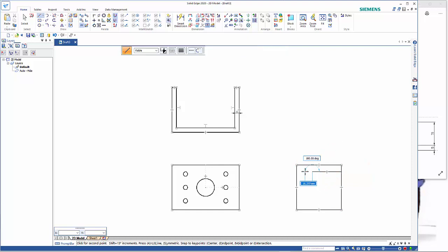If you come out to the left and hit the A key, that turns it into an arc. Then when I type in the arc radius, I can click to place that on the edge there. Likewise, I can do a fence selection on that if I hold the control key down to get rid of those extra bits that I don't want. Actually, it might be easier just to pick up on those, and then I can go to my mirror command, and if I click on a point here and just drag it out and place 2 points to define that mirror.